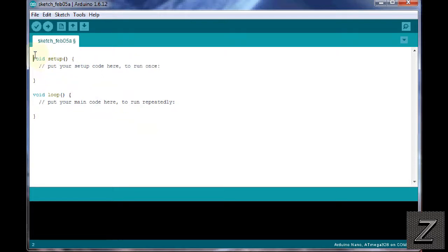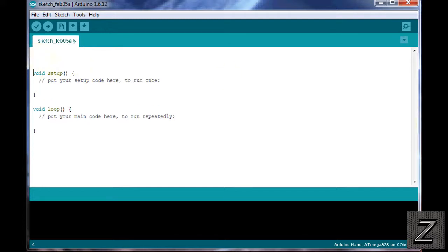Alright, so first, I am using an I2C LCD screen, and I do suggest using an I2C LCD screen. You can use the regular one, but you have to use more wires, and you'll also require, I do believe, a different library as well. But for setting this I2C LCD screen up, I actually have another video just on that, how to connect it up and get started with it. So I'll have a link to that on the website as well.